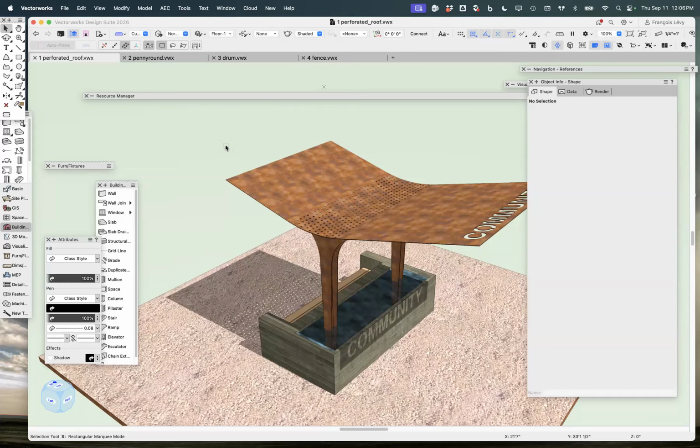Yeah. So if I just paste this over here, right? I've got this shell, and I made it a shell. This is neither here nor there, so that if it turns out that a 1/4 inch steel is not appropriate, I don't have to redraw this extrusion. I can just change that to, say, 3/8, and it just got thicker.